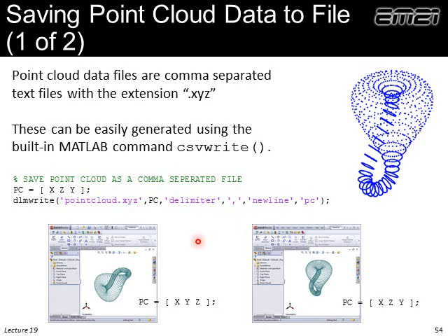Now, if we originally saved our points as XYZ, this is how we would like to think about it, but then when we read it into something like SolidWorks, it comes in lopsided. Remember, SolidWorks thinks that Y is the vertical direction, for some reason that I've never learned yet. So if we want to bring this into something like SolidWorks, we just reorder the points and do something like X, Z, Y. Now when we read it in, we see our object.